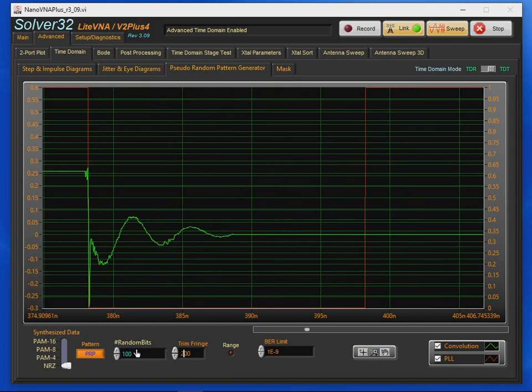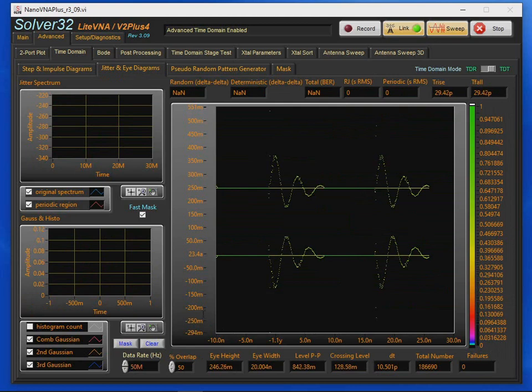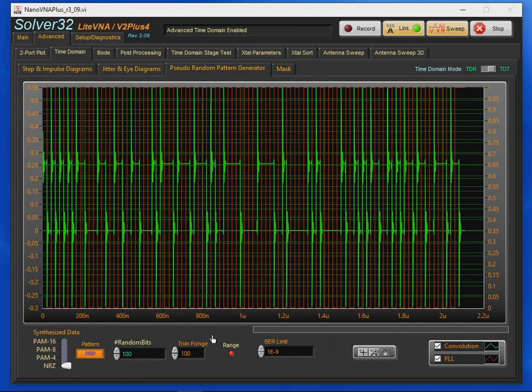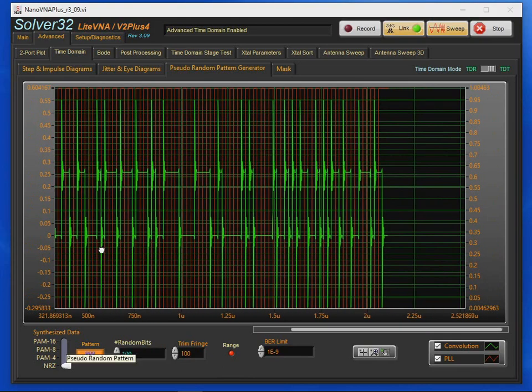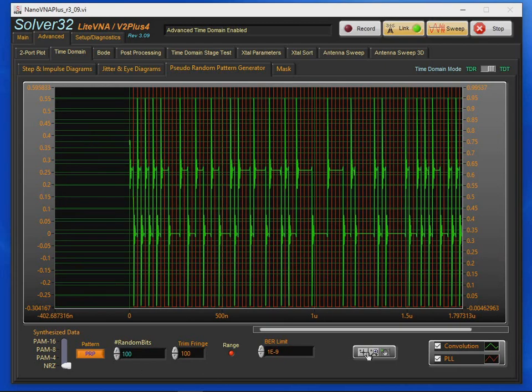Notice how we see that initial peak like we saw with the oscilloscope. And again, we don't model all the parasitics. But notice the number of data points. It's at 197,000. If we change our frequency lower, notice how this range flag gets set. Basically what I'm doing is throttling the amount of data that the software processes. Again, what we're trying to do is prevent the CPU from becoming overloaded. So that's the reason that I'm showing this particular circuit: there's actually a lower limit as well as an upper limit that we can measure with the LiteVNA.